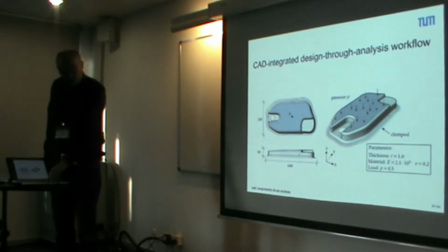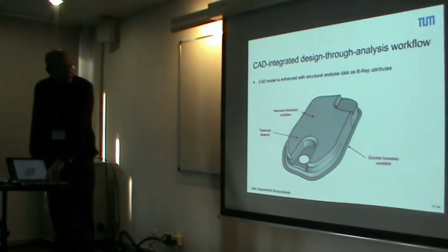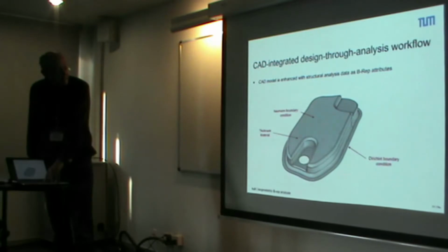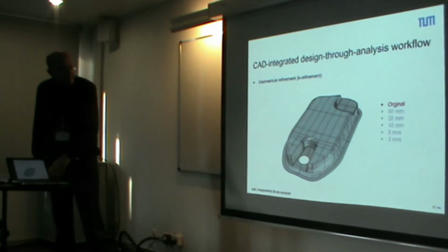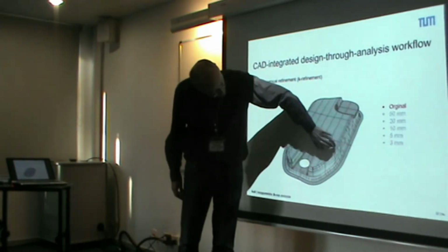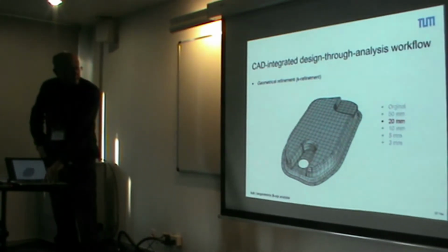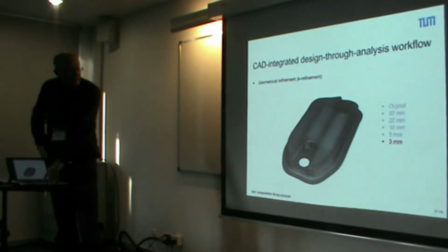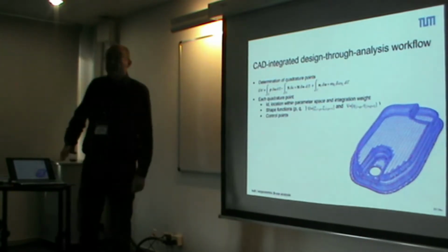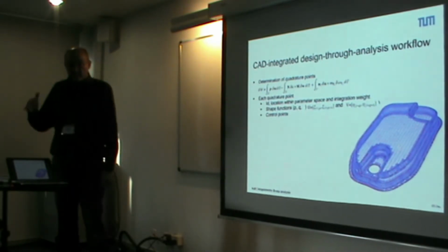We have the initial CAD geometry, where we add some additional information about the loading, the boundary conditions, and the continuity conditions. Then we have the individual parameterizations of the patches, as you see. Here we have the trimming edge with the individual surface parameterizations. On top of that we can also do refinement, and everything is driven by the information of the integration point, the Gaussian point, which, as I said, is the basis of everything that is done.